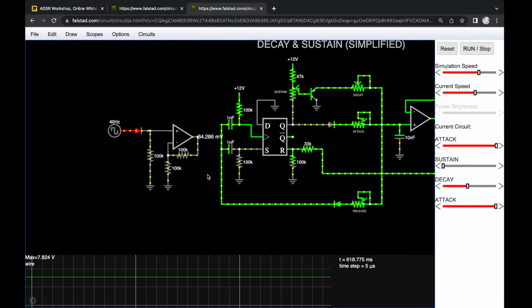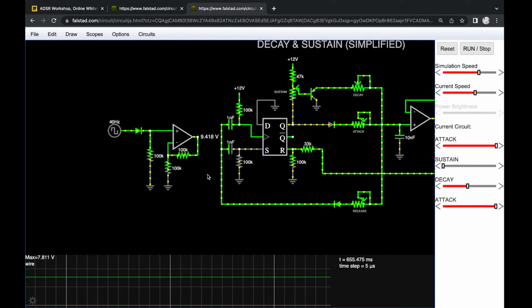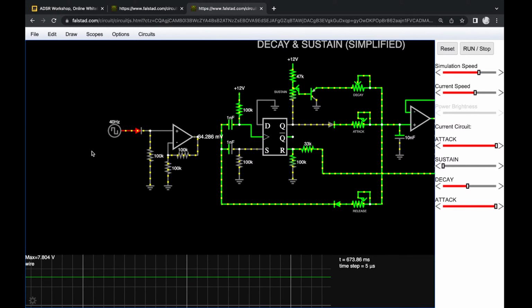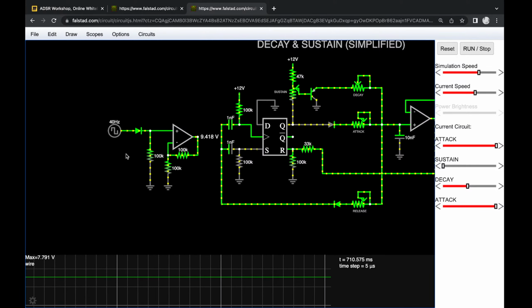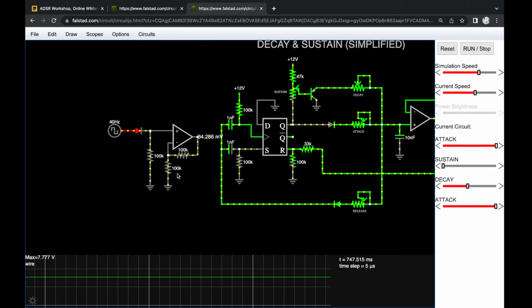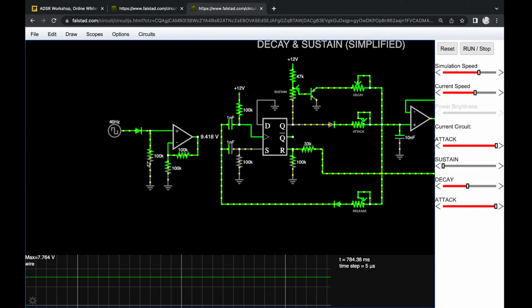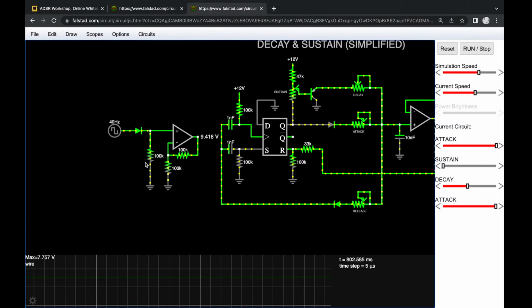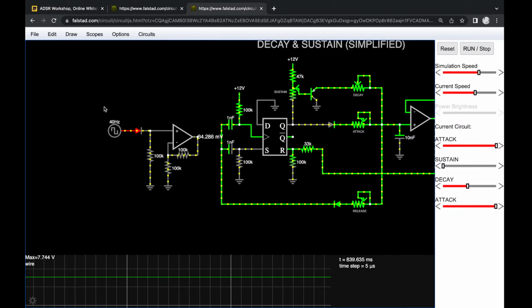And this is, I think, an okay solution, right? Because this will work with most clock signals that are at least, what do we need? 4 volts. You could increase the gain if you want to, but for Eurorack level gates, this should be okay. And this is also safe if the input is much higher.